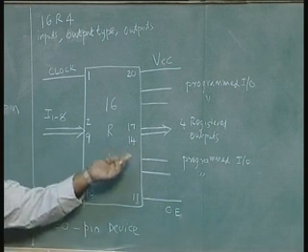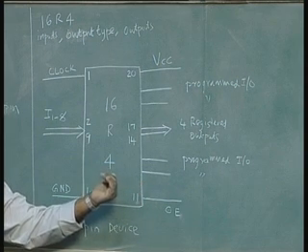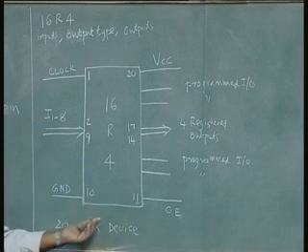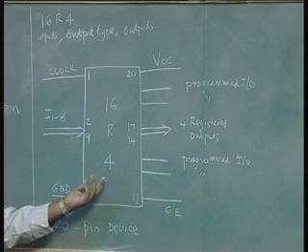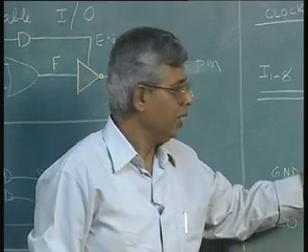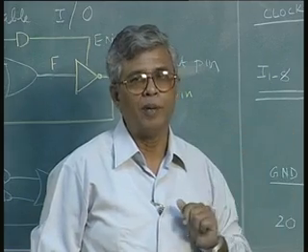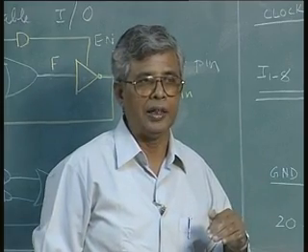You see, I have registers, I have programmable features, so I can increase the number of inputs, and I have a clock, I have an output enable function, and what else do you need? A moderate size design of a sequential circuit, which is driven by a combinational logic, can be designed using this and implemented using a single chip. So that is the beauty of the programmable array logic. All these features were developed in programmable array logic.